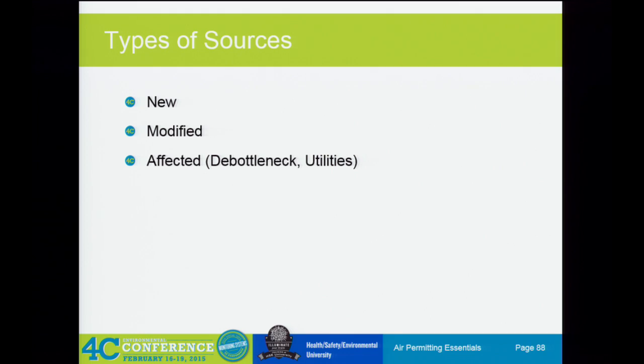So you have to evaluate the emissions from those sources. We'll be talking about how you evaluate those emissions source by source. The other sources that you have to look at are affected sources. Jim's gone through that. Can anyone remember what an affected source is? That's not a downstream. Anybody got an example? A baghouse. A baghouse would usually result in an actual increase in emissions, so a baghouse is tricky. Usually a downstream source would be like a boiler or something.